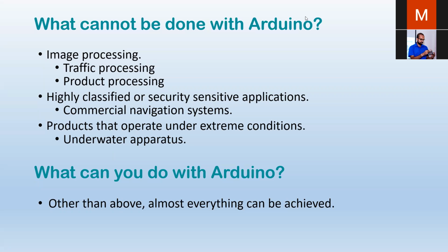There is a bootloader in the chip, and in some instances you can delete the bootloader and program the chip directly without using this Arduino stuff, right? Then you are using just the chip, the ATmega 328, and we call that bare metal programming. It is really advanced, and there are some advantages and disadvantages. It is really complicated and really hard to do.